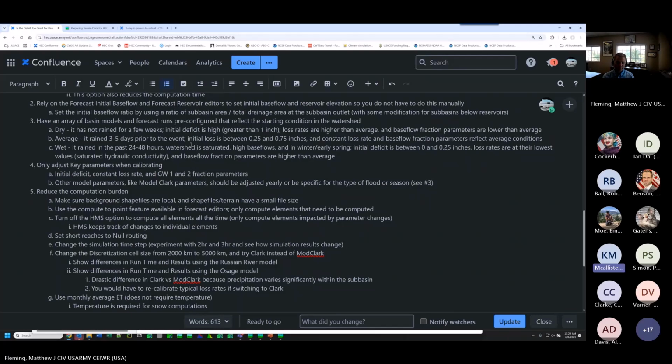Each time I don't create a new forecast; I take that forecast and change it and expand the time window. So the look back period changes and then the forecast time moves up. I've seen that works the best for me in our basins as far as trying to keep it calibrated.